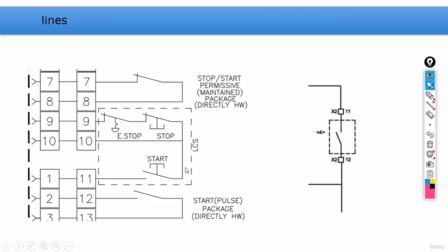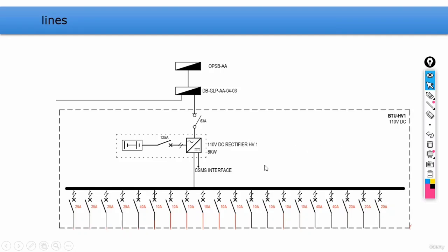Like, for example, here, the line is set all around the electrical symbols that we have for the push buttons. They are actually connected to the terminals, but this line here shows that the push buttons themselves are set on the door, for example. Now, we also have this contact set in this frame here, and the contact is actually connected to some terminals in an electrical panel. And, as I just mentioned, this frame here shows that the contact itself is actually set outside the electrical panel.